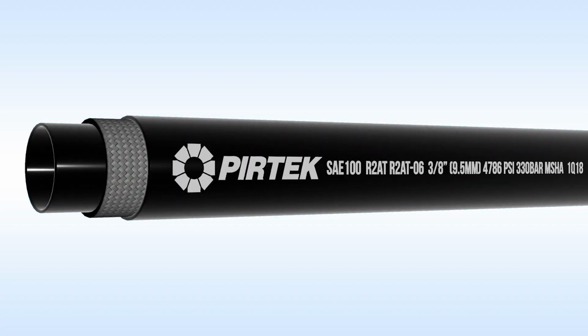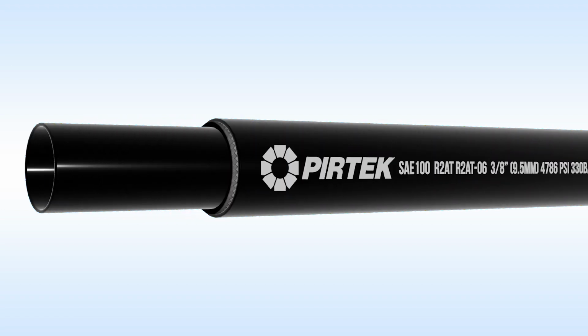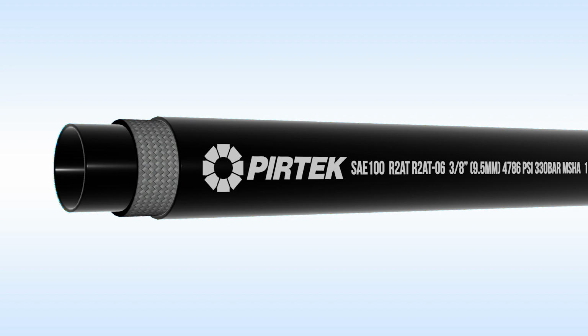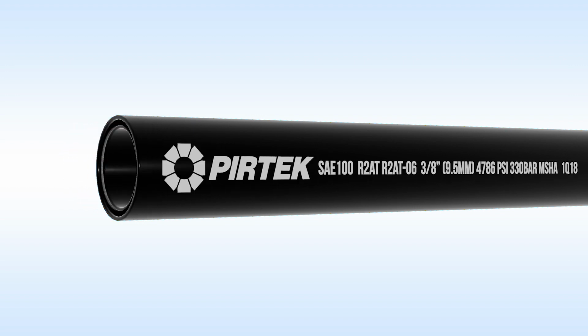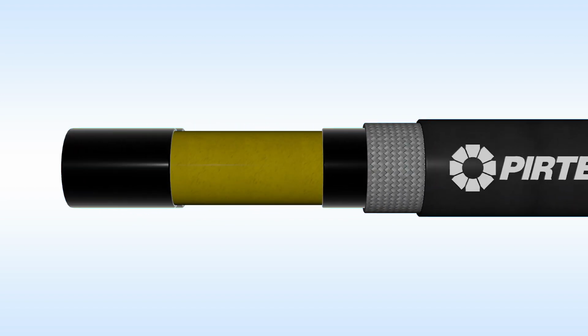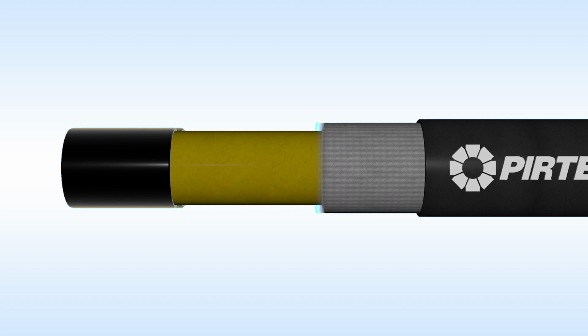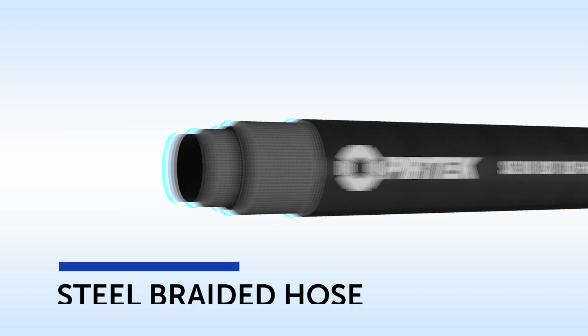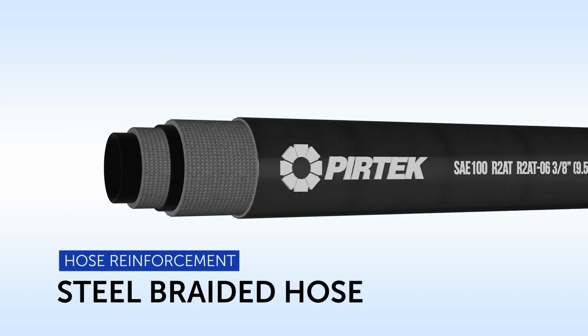A typical hydraulic hose is made up of three components: the inner liner, reinforcing, and the outer cover. A failure of any of these three components can lead to spillage and downtime. The inner liner is designed to convey the fluid or material running through it and is manufactured from various materials, including various rubbers, thermoplastics, and specialty materials. The reinforcement layer, or layers, contains the pressure. Materials used in the manufacture of reinforcing layers include polyester, high-strength synthetic cord, and high-tensile steel wire.